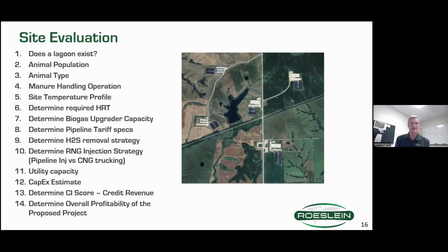We would also contact the local utilities for electrical, and if we needed any buyback natural gas. So we want to know what their capacity is, and can they handle the equipment it takes to do the upgrading. So we would give them an estimate of how much power we think we would consume, and then could their system handle it, and are there upgrades needed to supply that power?